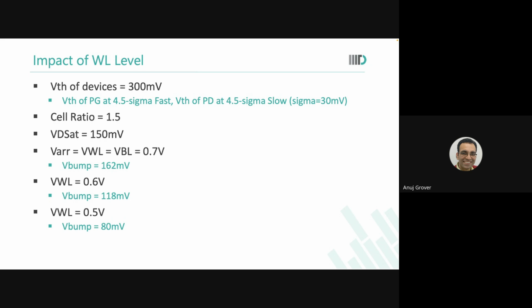And this is what we talked about in the rubric also yesterday, that this is a word line underdrive read assist scheme, but the read current goes for a toss. It's thrown out of the window. So it's not a 200 millivolt lowering of word line, even though it brings me that same stability. It's not what I can really do. I have to do a little bit of word line lowering, but that will not allow me to go to 0.7 volts over here.